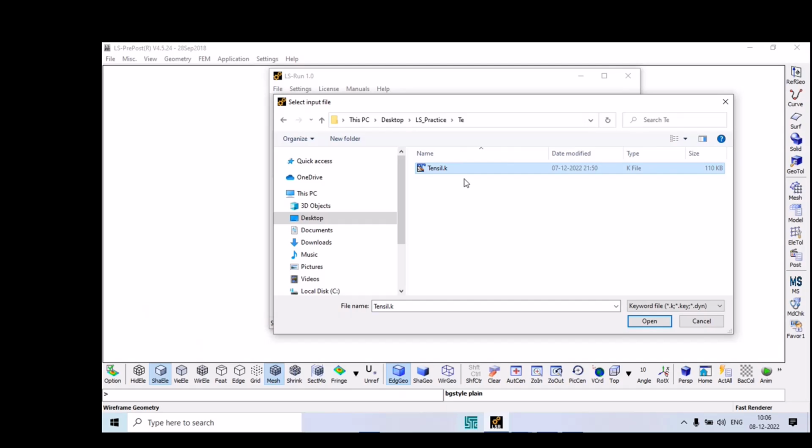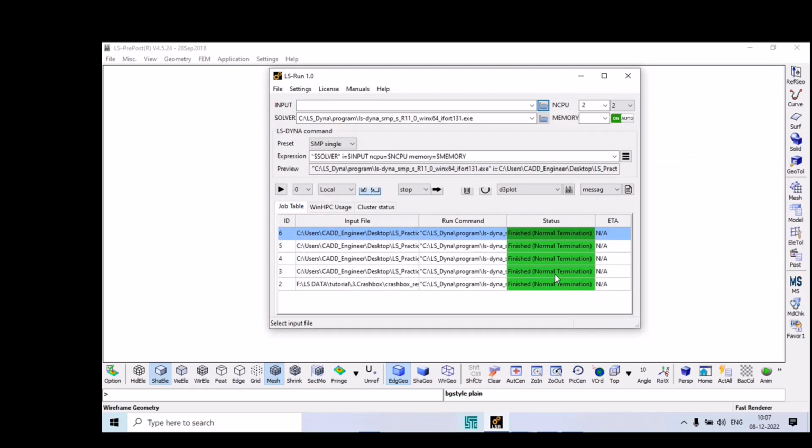Each time you make changes and want to see new results, use multiple folders so you can see the results of each simulation. Otherwise the software will overwrite the previous solution, and you won't be able to look at the previous one.